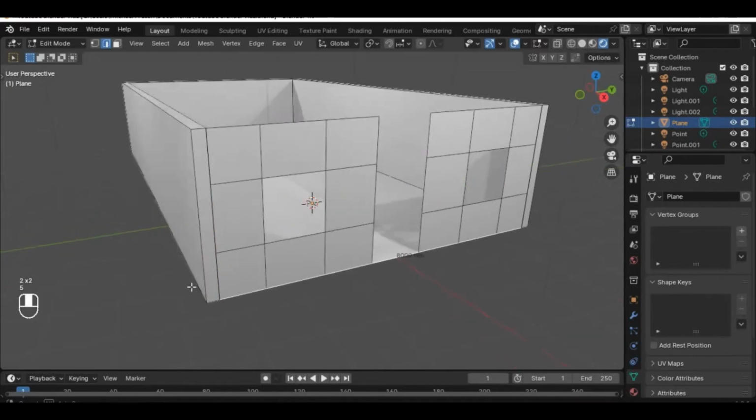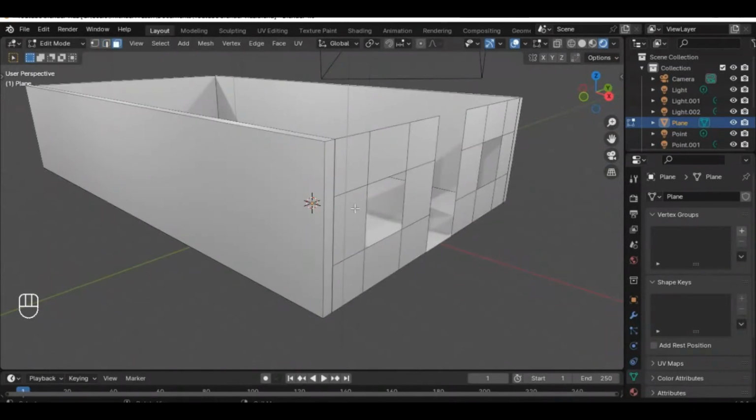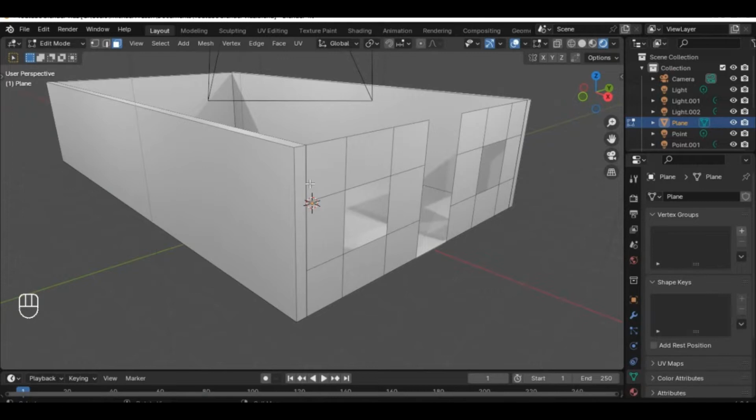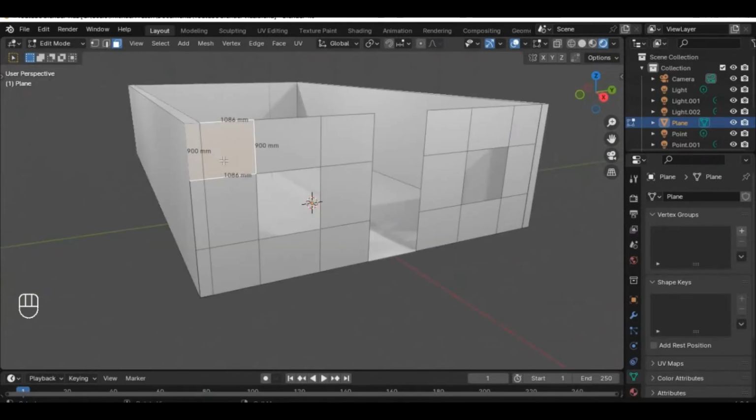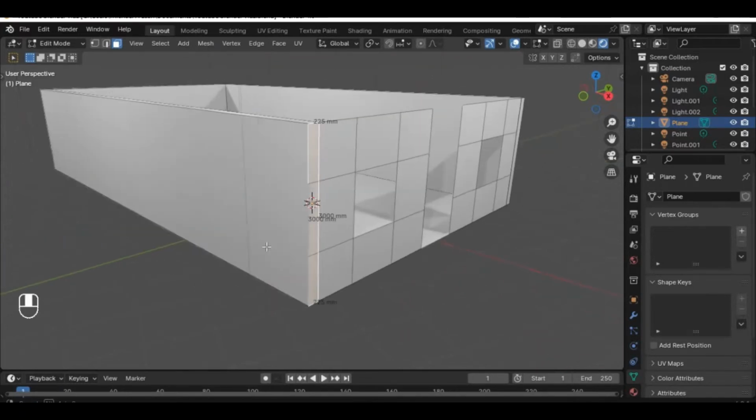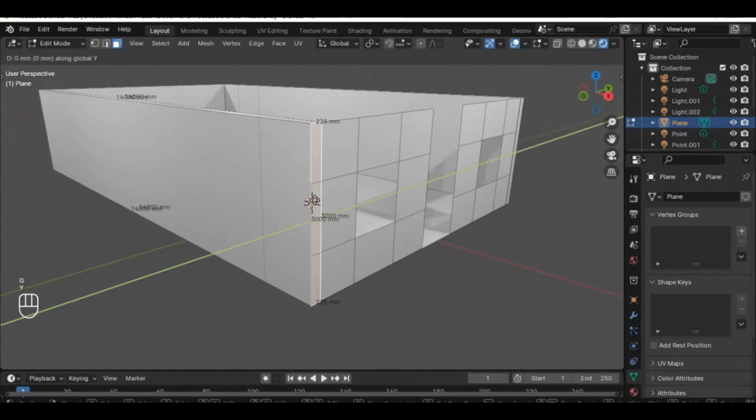Another method of doing it is, let's go Ctrl Z. Yeah. So let's go to face select mode now. I just want to show you another way to do it, because it can be very confusing. When you pick this face, you realize that this is the face you are picking, but you already know that this has a face, and you want to bring this edge back to this face. So what you just need to do alternatively is to pick this face that doesn't belong to this one, move it by 2.5, G X 2.5 minus.